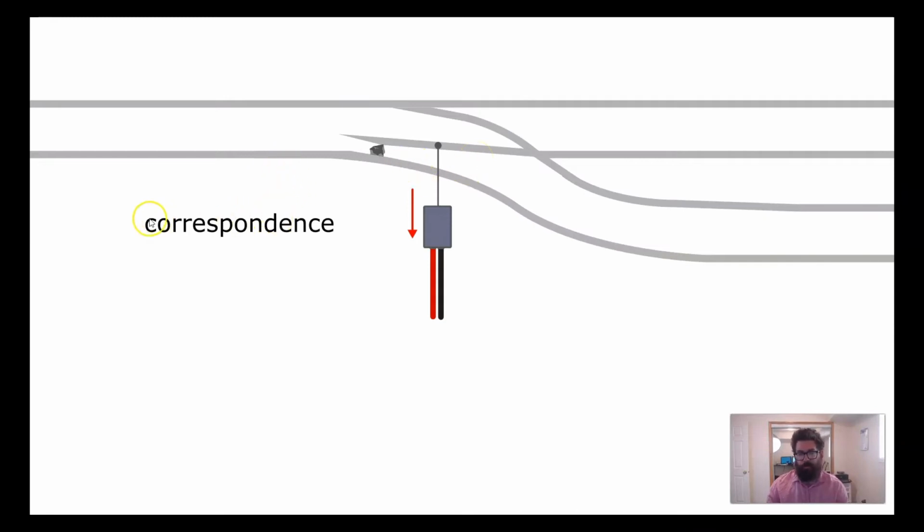And the notion of correspondence can actually be even more detailed than that. Sometimes there will be a check that not only is it in the target position, but that the GPI or the I/O are giving consistent feedback, which means in this case that it's not saying it's in both positions at once. So for example, to be in normal correspondence, that means that the machine wants to be in normal position. It is reading that it is in normal position, and it is not reading that it is in reverse position.